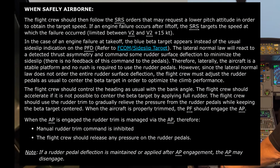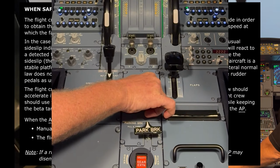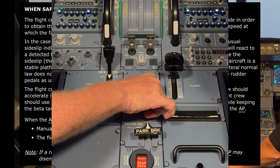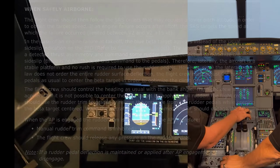Once the beta target is centered, use rudder trim until the pressure is relieved on your feet. Do not use a specific trim number. This varies depending on your aircraft's weight, speed, and environmental conditions. Trim the rudder enough to feel no further foot pressure is needed to maintain the rudder pedal position. If your rudder is fully deflected and the beta target is still not centered, increase airspeed to improve rudder effectivity.